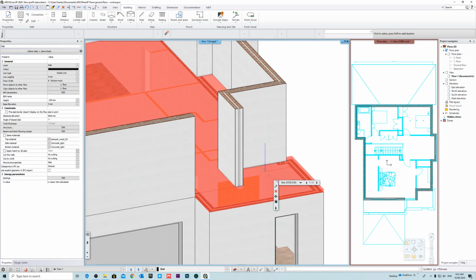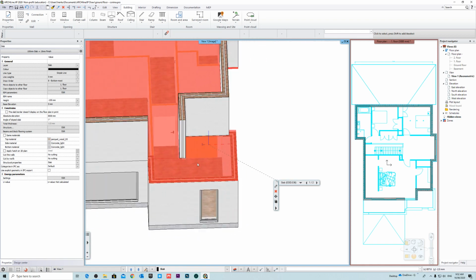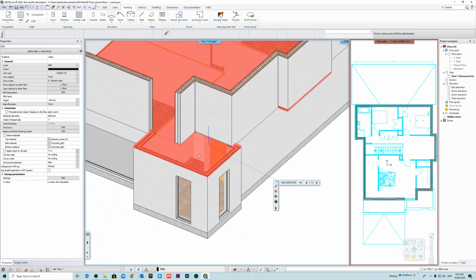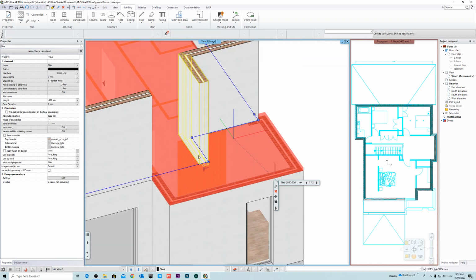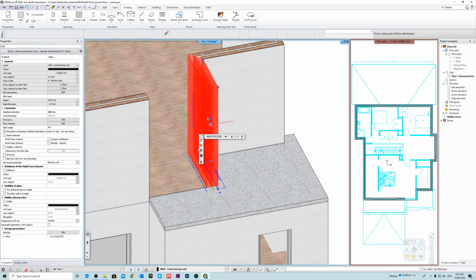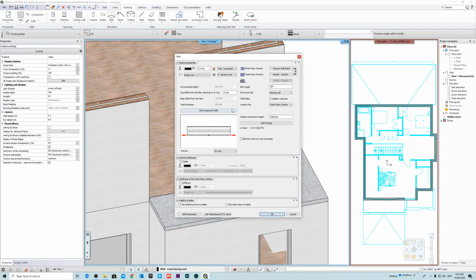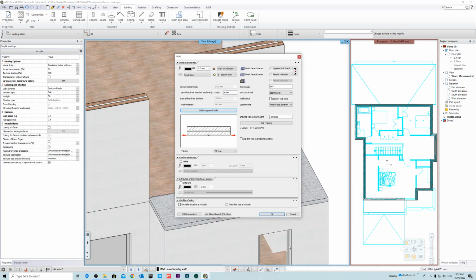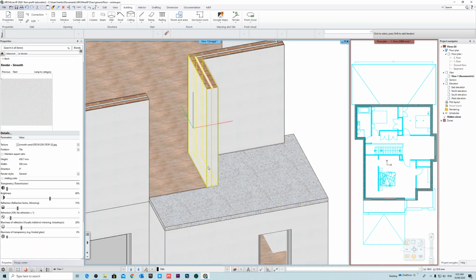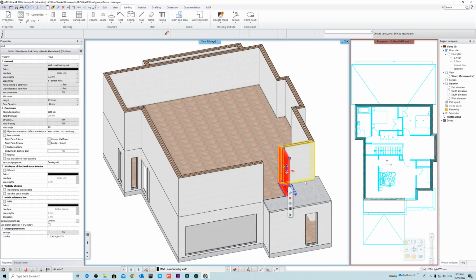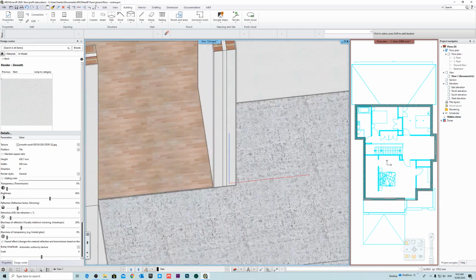Now, I don't know, in structural terms, this might require a beam running at the bottom. But essentially this is just going to sit on top of that. So we'll go here and do the same thing. I'm going to go edit compound walls and just go like this, and we're just going to hit rebuild. Now you can see that's looking good.